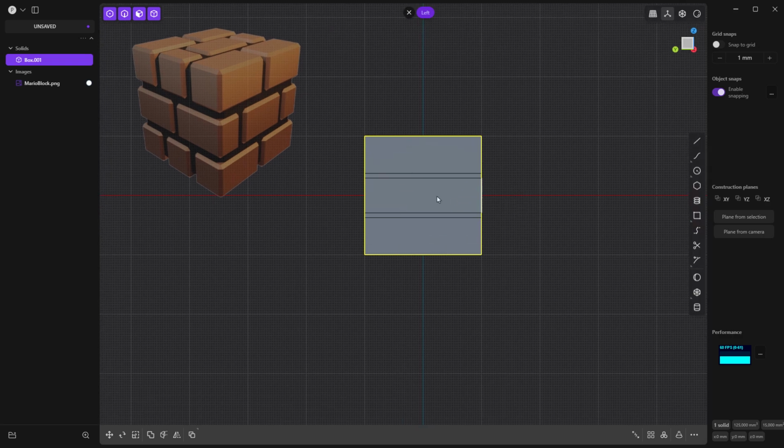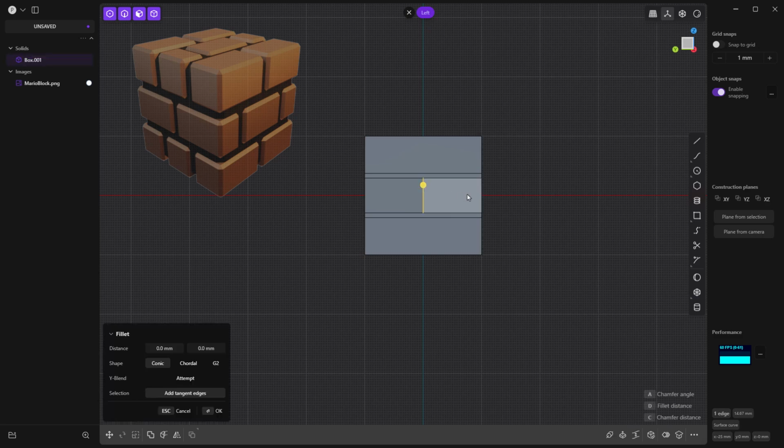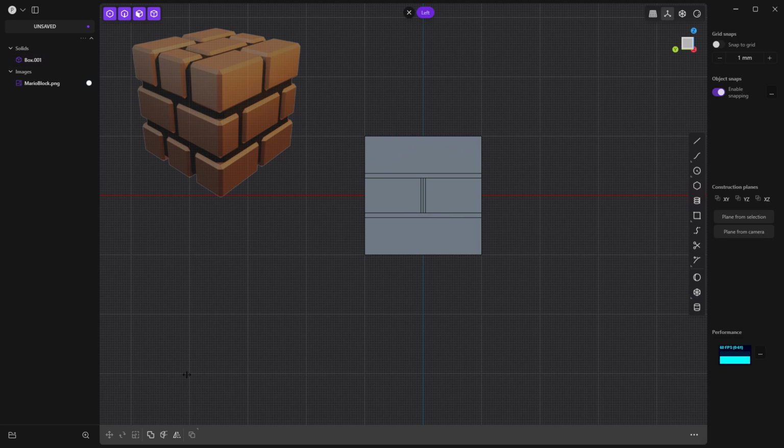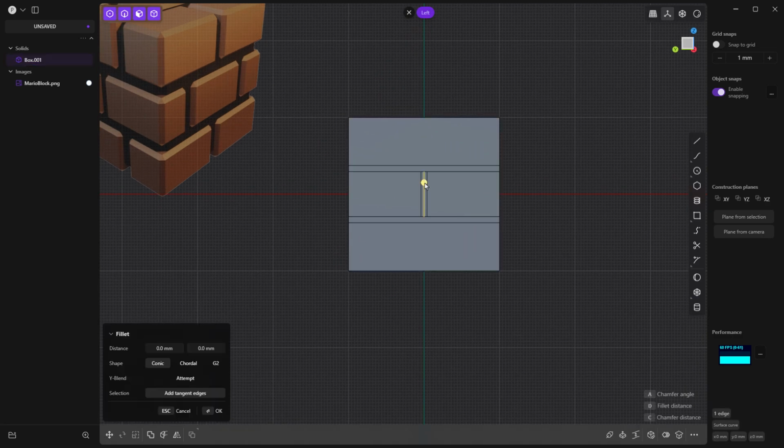So now that we've got this sort of orientation here, in the center, we're going to be divided right in the middle. So this is once again where isoparam comes in handy. Control R, then Tab, and just simply snap it there. Once again, we can use offset, so O, Tab, and set this at 1 millimeter, and then delete the original.